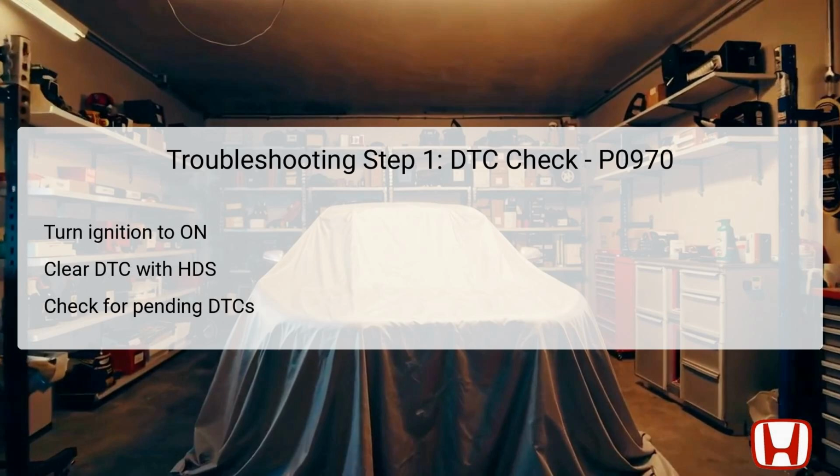Once the wait is complete, use the HDS to check for any pending or confirmed DTCs. If DTC P0970 is confirmed again, it indicates that the issue persists and further steps need to be taken. If the DTC does not appear, further investigation is required, as this may suggest a transient fault.